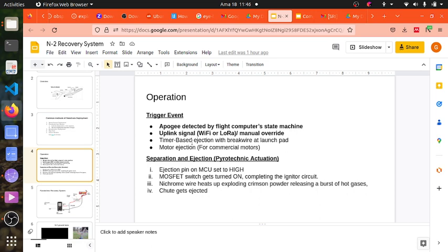Once that happens, a countdown timer begins to count down, and then at the end the parachute is deployed. So let's say you've set the countdown to 30 seconds. Once the rocket takes off, the break wire breaks, the countdown begins, and then after 30 seconds the parachute is deployed. So this one is also used, but we haven't used it at Nakuja.